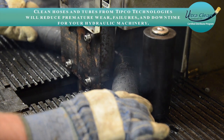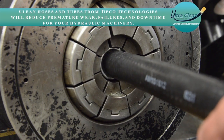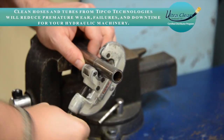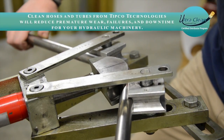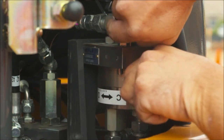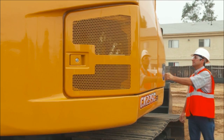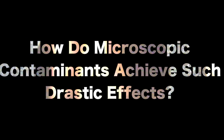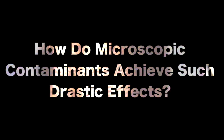Contamination is generated in hydraulic hose at the time of cutting and crimping. Contamination enters metal tube assemblies during the cutting, deburring, bending, and flaring processes. Hoses and tubes that are not cleaned before installation will have a detrimental effect on any hydraulic system they are being installed on. How do microscopic contaminants achieve such large and drastic effects?